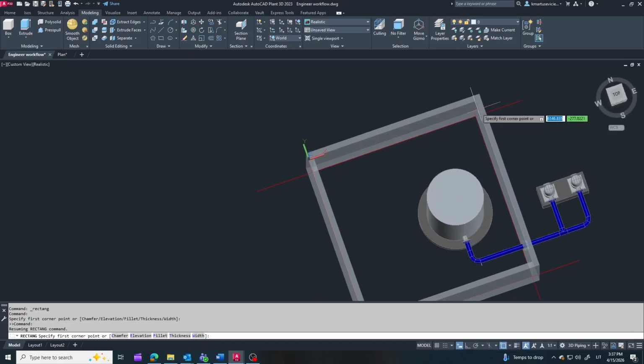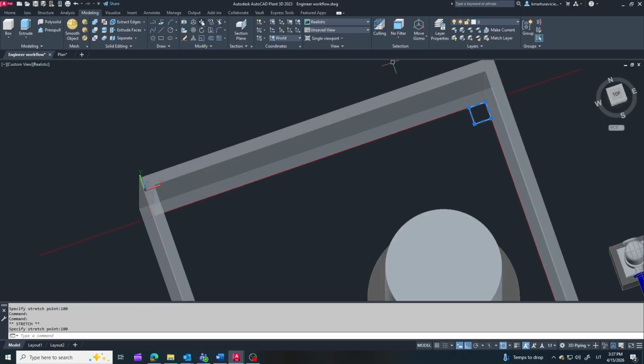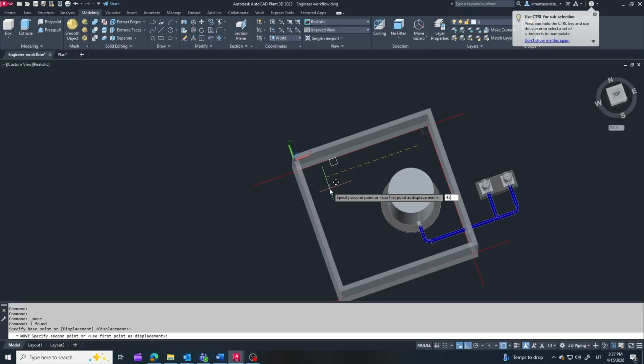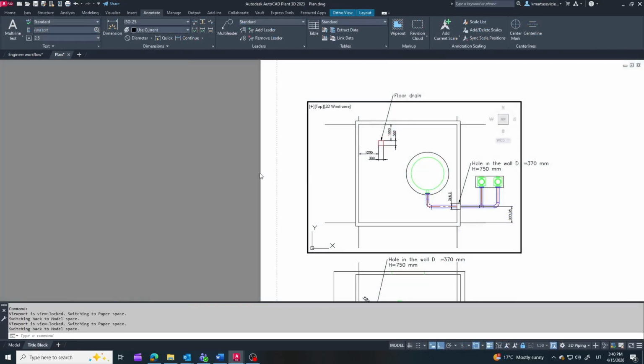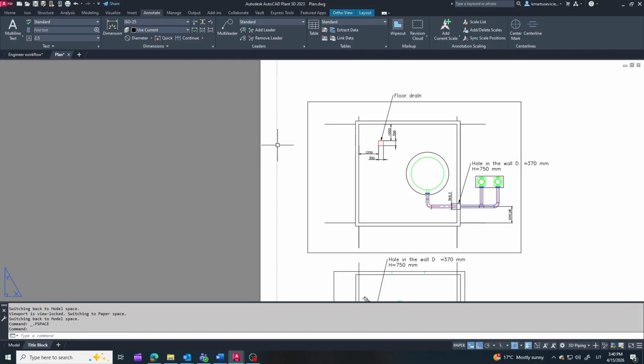In this part, we continue the project, developing the layout, refining tasks, and moving closer to a real engineering solution. Now a task for the plumbing team. I create a floor drain in the room, and the plumbing team will route the sewage pipes under the floor. My task here is to show the location of the drain pit. Sometimes it's enough to show just the location point on the layout plan. Now I relocated it to my layout drawing and added a simple annotation.